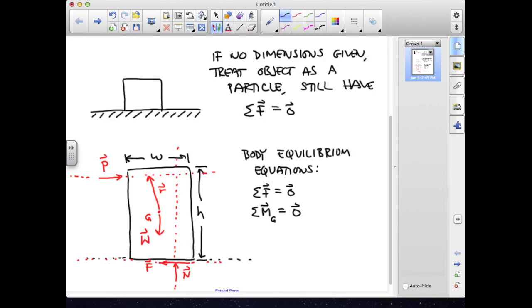Along a similar line, if I'm exerting a push through P, that's going to tend to lift the object off the ground and reduce the pressure between the object and floor near P and increase the pressure away from P. The normal force N represents the integrated sum of this pressure over the floor to find a total or resultant force, and the fact that it's off-center is indicative of the pushing force tending to cause this change in distributed load at the floor. How do we find the center of N in a case like this?